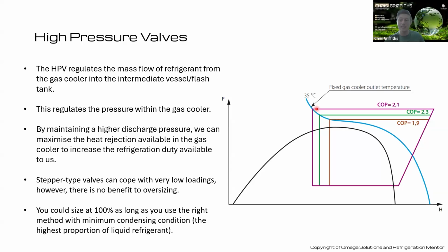So we effectively oversize a valve, but we're going to have issues with oversizing in terms of cost and then control at higher conditions as well. The manufacturer software will generally say between 15 and 85% okay, and it'll try and give you a proper band, normally between say 50 and 80% where it wants to target the selection.